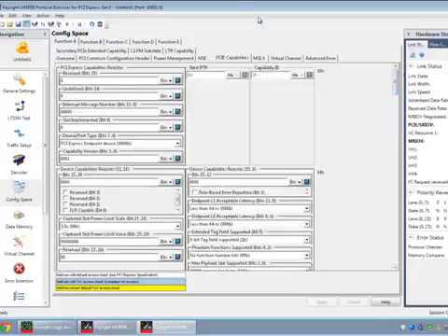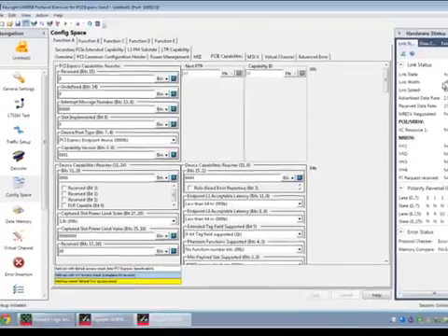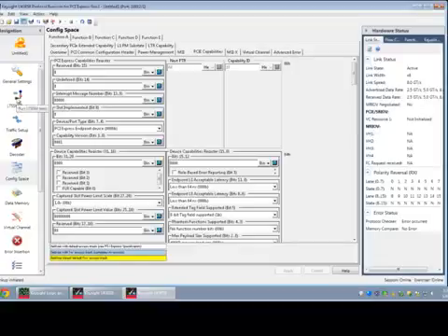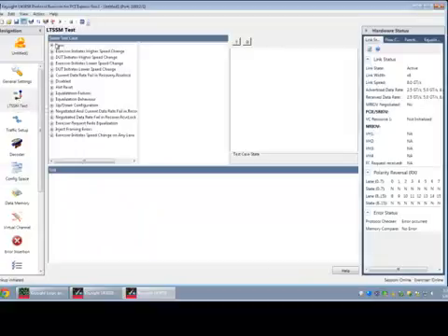So now across the top, I go to my link, start link training, click on that, and I see my link is up and active. I'm operating as the root complex, testing the device. How do I know if I'm going into the L1 substate? Well, now I go into a quick LTSSM test. LTSSM test has all my basic operations for testing that configuration.